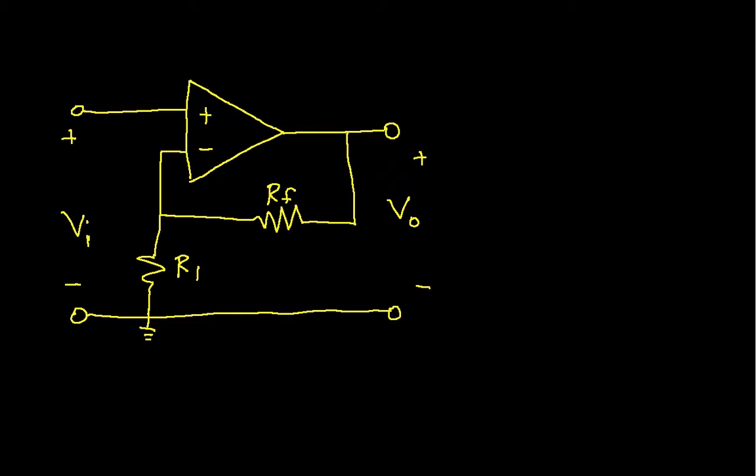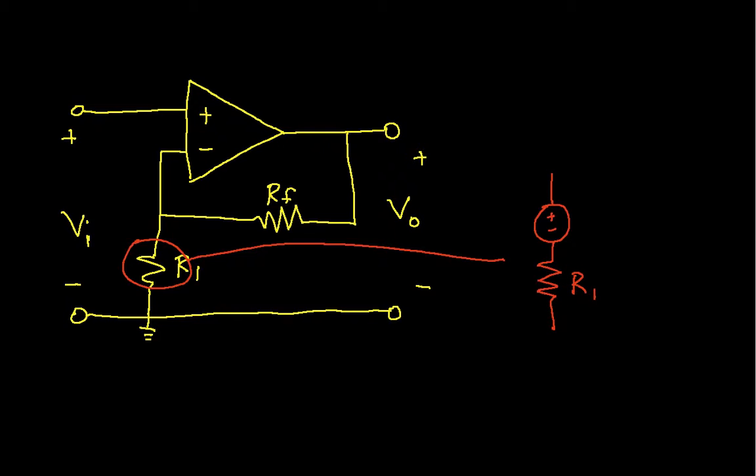Typically the way we do this with resistors is to take a real live resistor, something like this in a circuit, and model it as a noise source, which models the thermal noise generated by the resistor, and then a noiseless resistor. Now, you just have to keep track of which type of model we're using because there's not a separate type of symbol for a noiseless resistor.